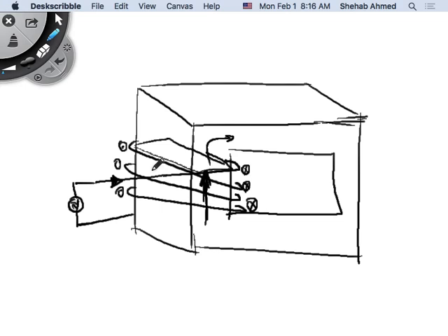This flux phi here will be a time-varying flux, because if you don't have a time-varying flux, we said that we cannot generate a voltage at all, right? So we will look at the equation shortly. But if phi is a time-varying flux that is crossing a big, nice cross-sectional area that is not laminated, then what's going to happen? This big cross-section area is like a short circuit, right? It's a big conducting area for the current to flow.